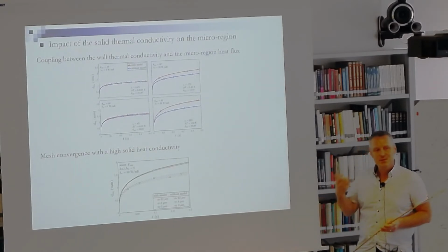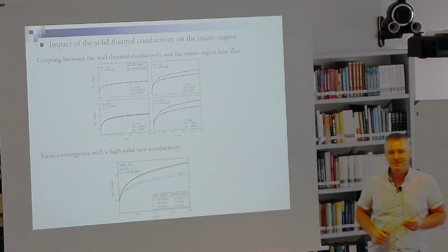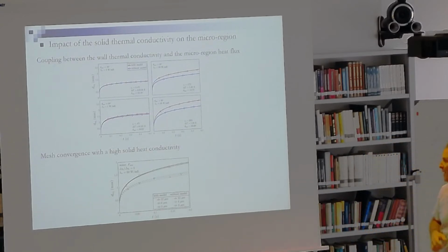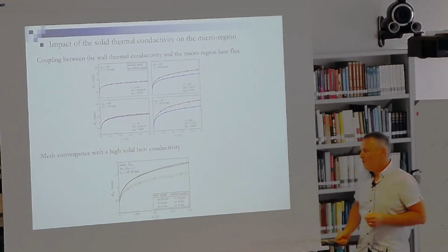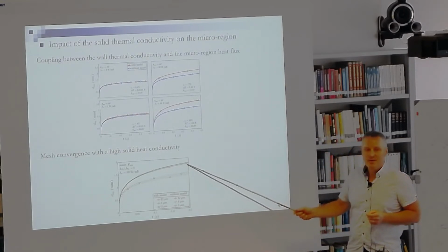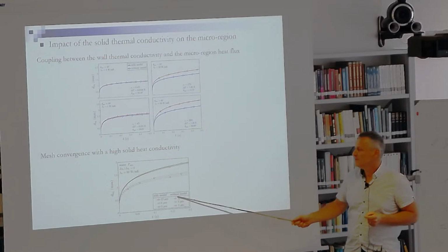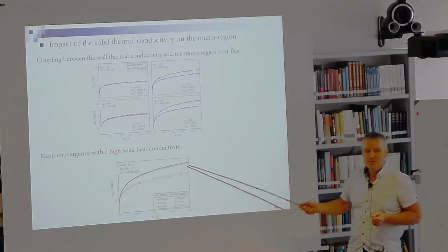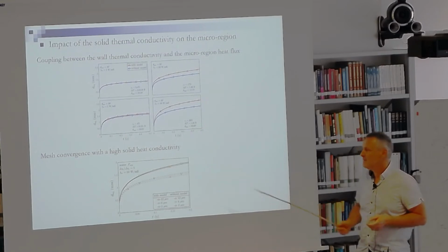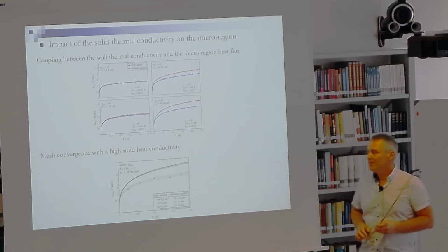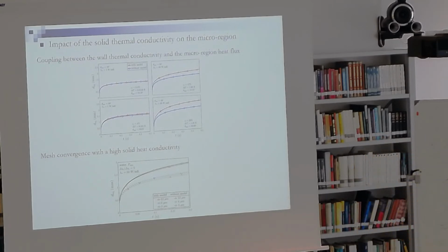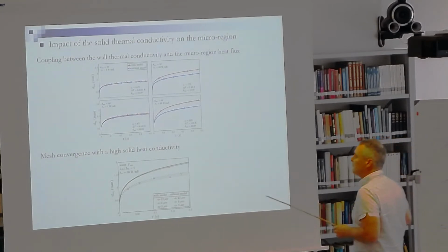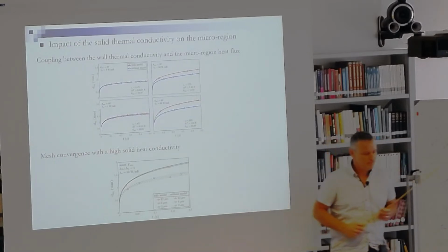There's a kind of difficulty to converge because the thermal field is a bit singular in this region, especially for high wall thermal conductivity. Whereas in the case we use a model, the space convergence for several mesh sizes is much more evident. So we have a model that integrates new physical effects, but also it improves the convergence property of the overall solver.